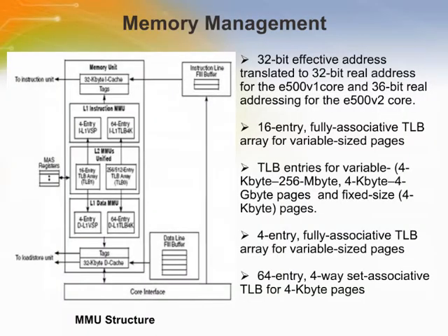The E500 core complex supports demand-paged virtual memory as well as other memory management schemes that depend on precise control of effective-to-physical address translation and flexible memory protection as defined by the architecture. The mapping mechanism consists of software-managed TLBs that support variable size pages with page properties and permissions.